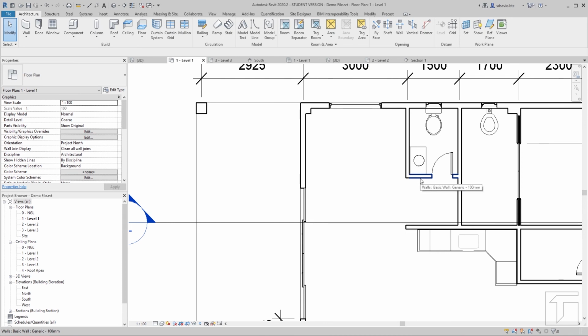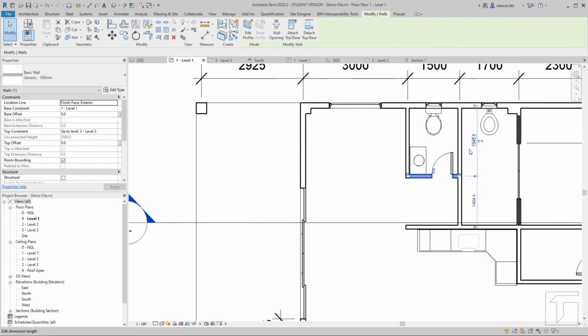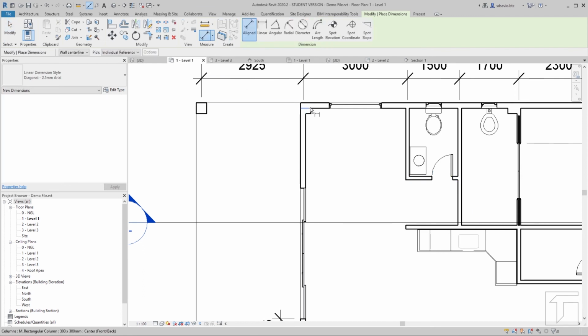So again, if we are in Revit, it's very easy to edit things around. So select that. Oops, so there you go. It's not yet 2000, so we just type there 2000, so that before we dimension this wall here, it is already correct. So the other location of that dimension command is up here on the modify tab or modify menu. We have this command here, so you click on that and we select this wall here to this wall here, and then we snap it into place.